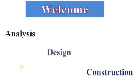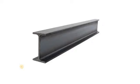To understand shear connection and moment connection, we need to learn certain basic things. Let's consider this I section. This is the web and this is the flange. If this section is used as a beam, can you tell me which part carries the shear force and which part carries the moment? Well, if you don't know, the web carries the shear force and the flange carries the bending moment. But why?